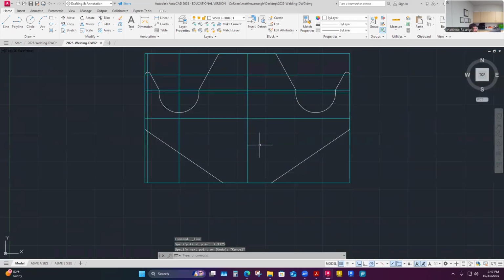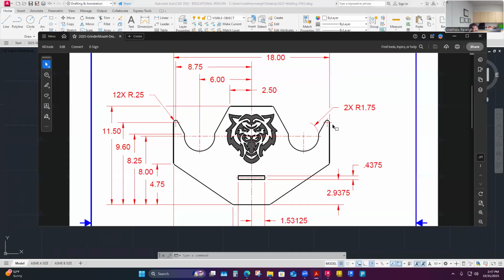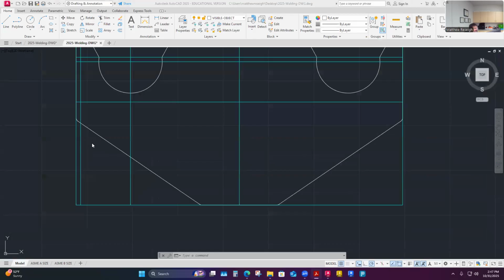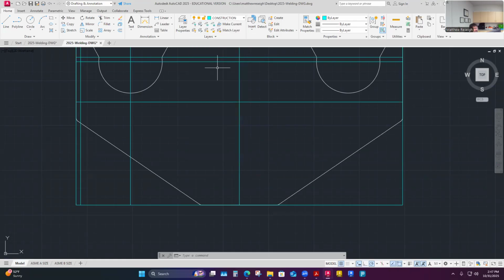I'm going to show you just one way. Sometimes we as drafters will draw geometry and then move it to where we want it. So maybe I do need a construction because it's weird. I don't have the center. In order to place stuff, sometimes like this kind of geometry, I would place it by center maybe. So I technically don't have a great indicator for this, 2 and 15/16. So I might draw one line, and I might draw a line over a line here. So I might break my own rule. Sometimes I add another layer that's a different color, and it's another construction layer.